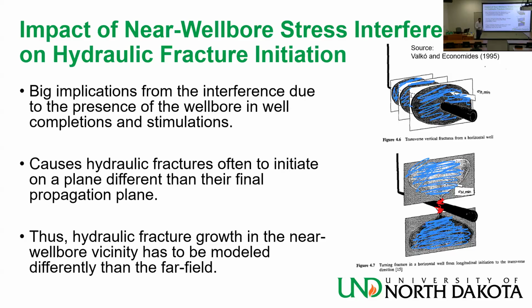If you get a screen out, 70% or 60% pumping is over for that stage. Forget about it anymore. You're not going to propagate any more fractures in that stage. Move on to the next. There are things you can do to mitigate that. It's better to try to prevent it than mitigating it after it happens or suppressing it. But yeah, early screen out is a bad idea.